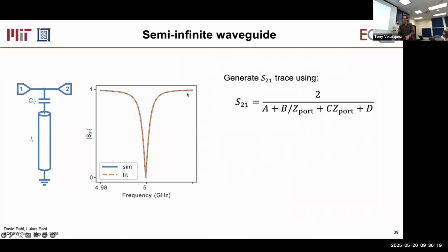All right, we've talked a lot about where the frequencies of our resonators land. If we zoom into one of these resonances that so far look more like lines and dots, we see a Lorentzian line shape that goes down and up and has a certain width. And this width here refers to this line width, kappa. We're also interested in accurately getting that, right? Not just the resonance frequency.